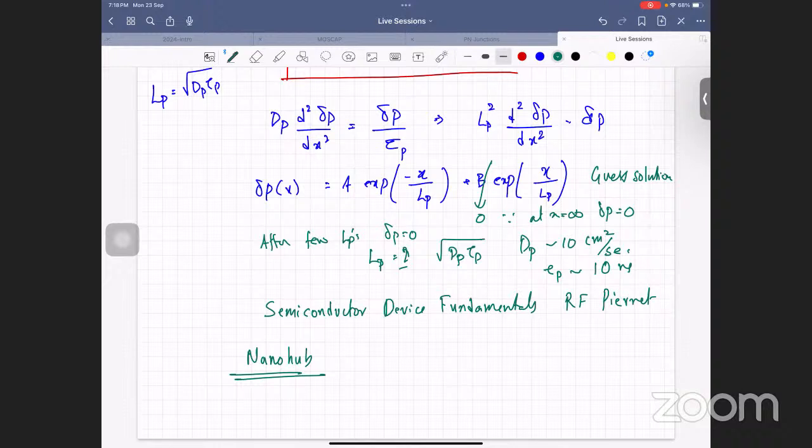Generally, when you increase the doping concentration, you tend to increase the threshold voltage. But put in the concentrations, because finally what you'll have to look for is what is happening to C depletion. Put it in the NanoHub simulator and observe what is happening. That will be a better way of dealing with it.